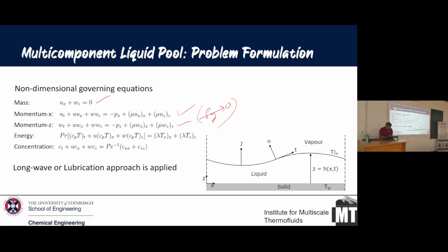Now, if I look at the energy equation, you've got the temperature, you've got the usual energy equation here. You will see that lambda is the thermal conductivity and things like that, so you'll have the effect of that. You also have the concentration equation. Now, the concentration equation, I have done some tricks here. One of the tricks I have assumed is that this is only the liquid phase concentration equation. Okay, so this is the concentration equation in the liquid phase.